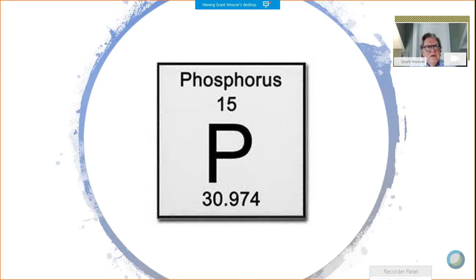Once you get a handle on that, then work on your expertise in phosphorus removal and some of these counterintuitive things. And by counterintuitive, I mean to get better treatment, turn the air off. Not what we are comfortable or used to doing. Learning how to react for the nitrogen removal is going to help in the phosphorus removal.